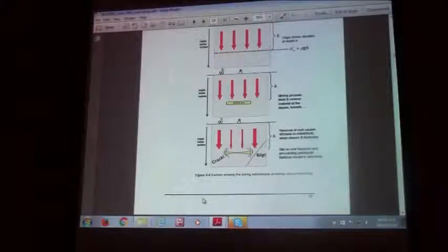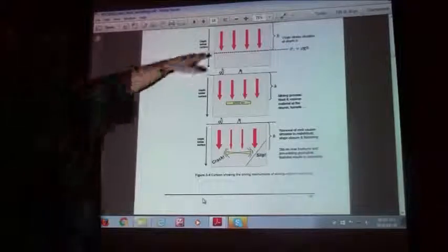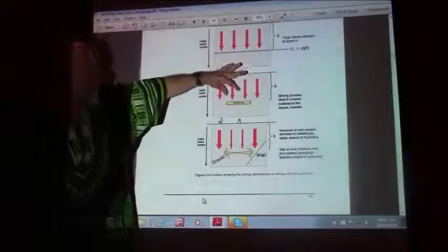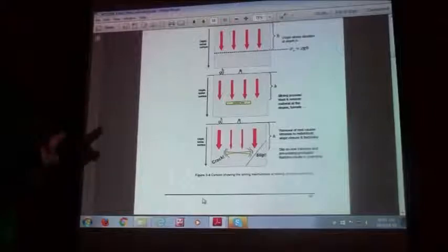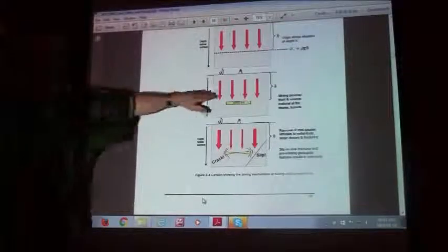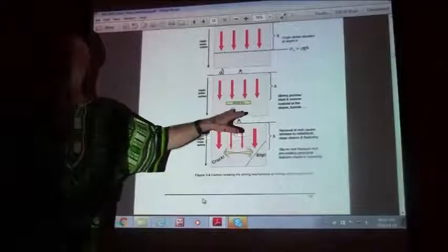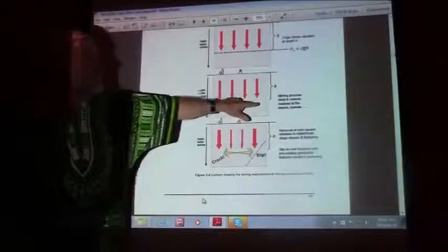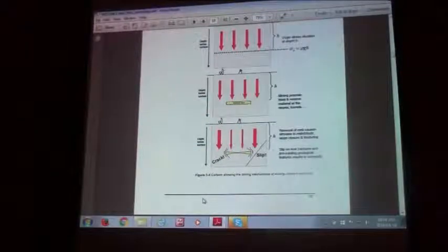But in mining, where does the energy come from? Well, it's quite straightforward. If you've got a solid earth over here, the rock has weight, so it has a load down below, and the moment you start making a cavity, an excavation, the force that would have been transmitted through that cavity has to go somewhere. Okay? It gets diverted around your opening, and your stress gets concentrated around the outside here, so you get big increases in stress around your excavation. And you get to the point where the increase in stress becomes greater than the strength of your rock.